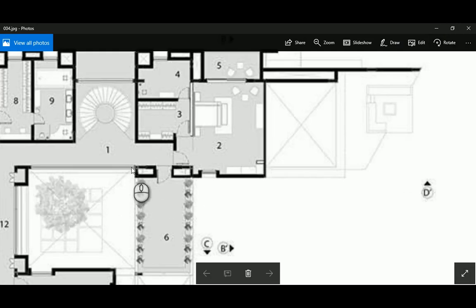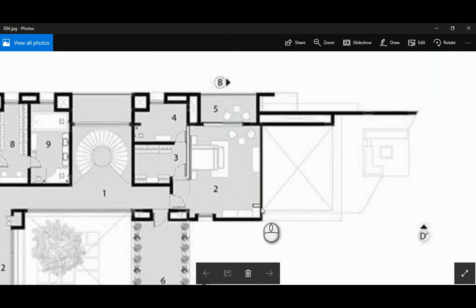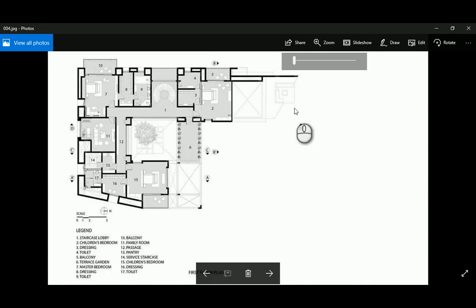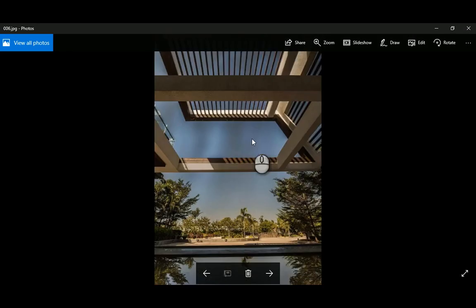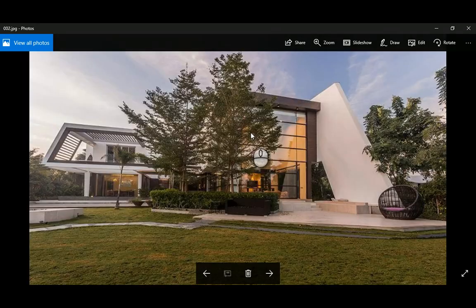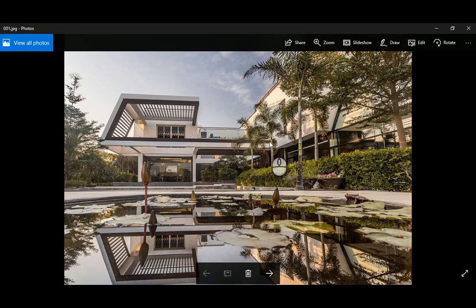So like a 500 setback here. So that's normal glass. It isn't set back. This part is actually getting ahead, or cantilevered, and the inclination starts from here going that way. Again, you're going to see that in the pictures here. So in order to do so, I'm going to make all of it a conceptual mass and then apply wall by surface to it.